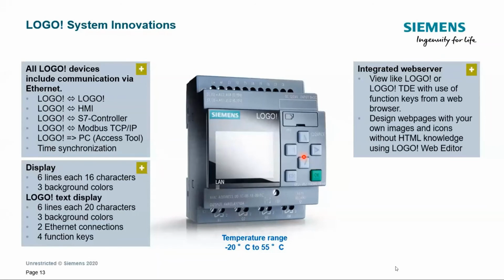Another nice feature is the integrated web server of LOGO!. This means that if you are connected to the Ethernet port of LOGO! and you try to reach the IP address of LOGO! over a web browser, you have predefined web pages that make up the web server of LOGO!, and by default, without doing anything, it gives you the option of displaying the same display messages you configure for the integrated display or the LOGO!